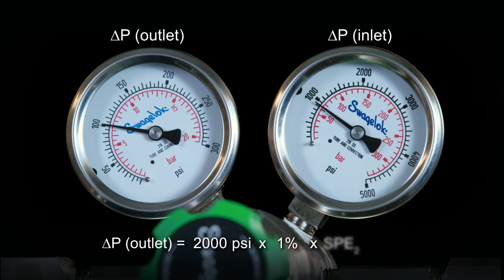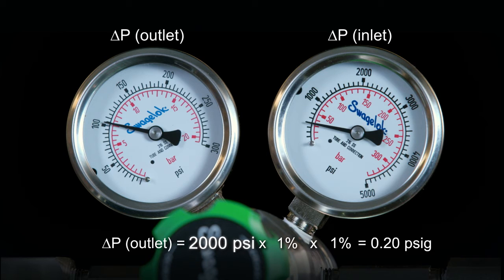As a result of that increase, the second-stage regulator will experience a 0.01 bar or 0.20 psig decrease in outlet pressure. The net result is a minimal pressure decrease that is only 0.01% of the initial cylinder pressure drop. 0.01 bar or 0.20 psig equals 137 bar or 2000 psig times 0.1 times 0.1.